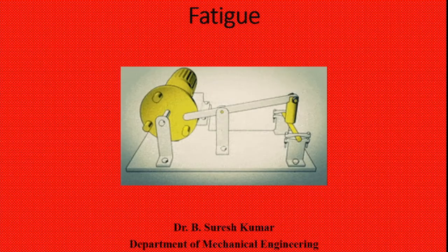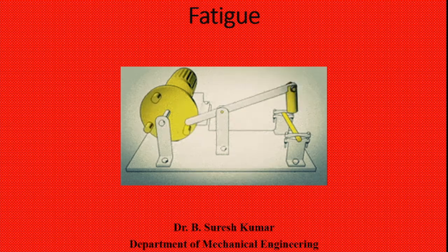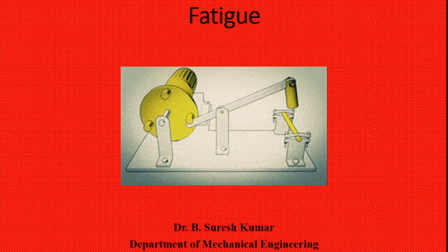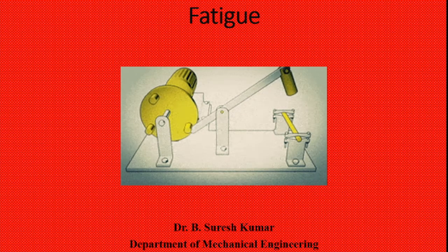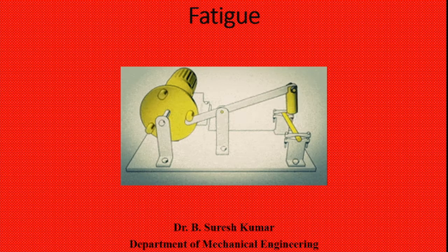Here, what is fatigue? Fatigue is one of the properties, the tendency of a material to break under conditions of repeated cyclic stresses. In the picture, a cyclic load is applied on the clamped workpiece so that the material gets deformation. Due to that deformation, the material undergoes fracture also. The fatigue fracture is caused by the propagation of cracks that initiate at a single point or at a few points in the material, so that the material gets damaged or fractured.